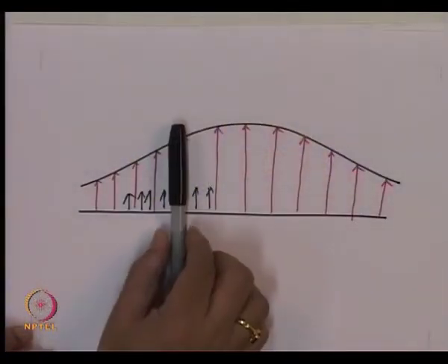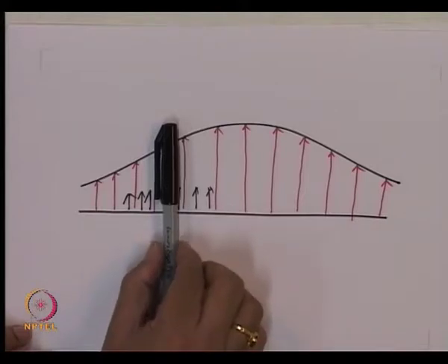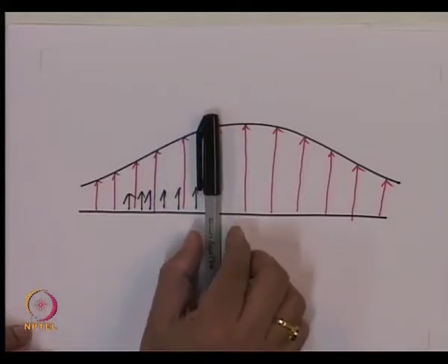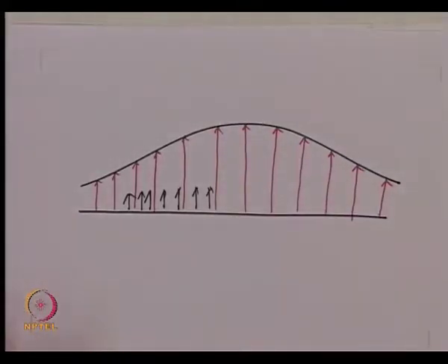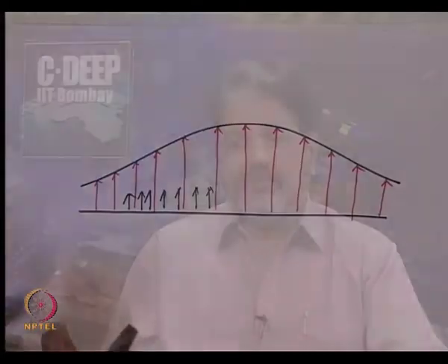So, essentially what we are saying is that the pulse which rides on this carrier travels with a certain speed, the pulse which rides on this travels with a different speed, this with a different speed, and so on. And because of this different speed, the pulses riding on different carriers reach at different times, or they take different times to propagate a given length of fiber. And that is what essentially gives rise to what is called the material dispersion or intramodal dispersion.